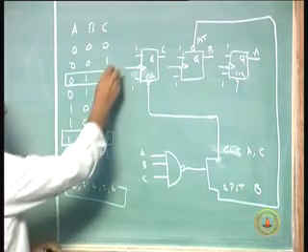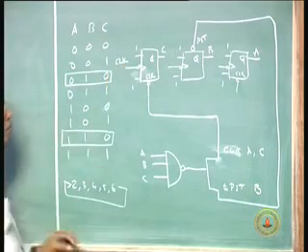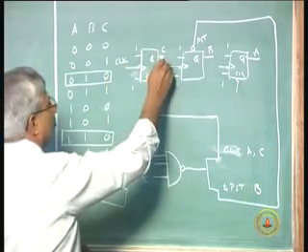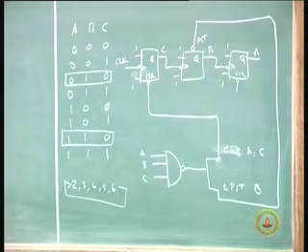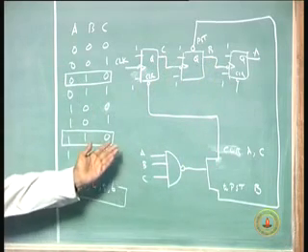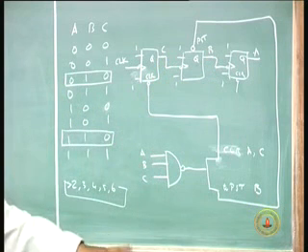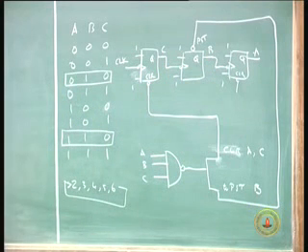This is my input clock. This is a counter which counts from 2 to 6. Yes? So here only in the second cycle it starts counting from 2. So in the first cycle it's counting from 0 to 6.